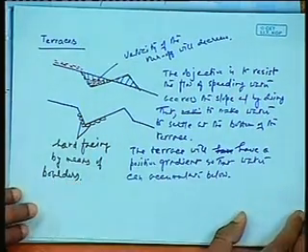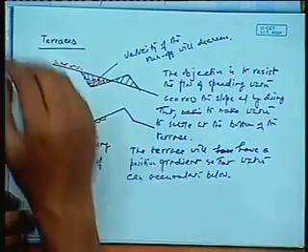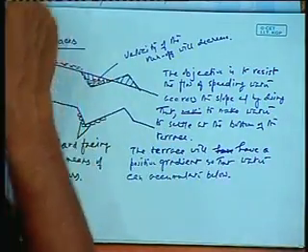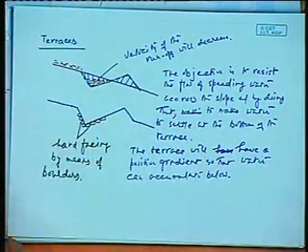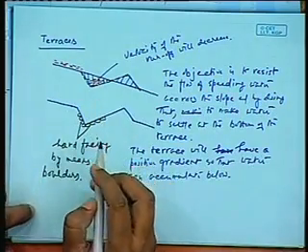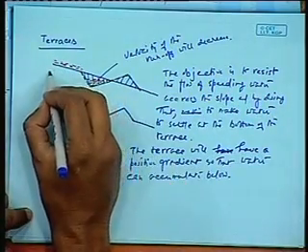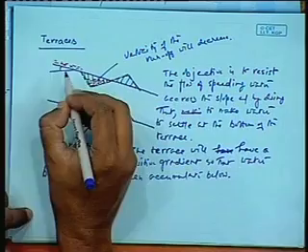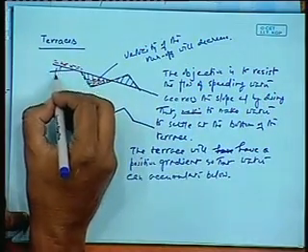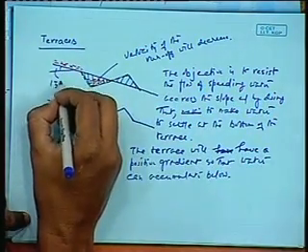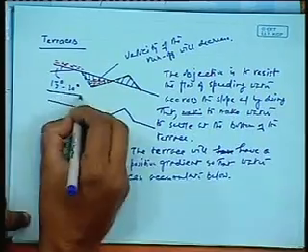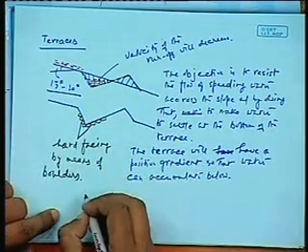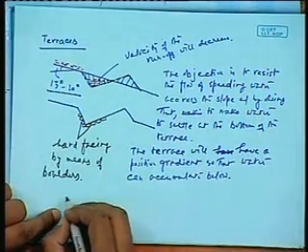So this gives you one kind of terrace. This is called when the slope is gentle. See, the slope here, if you can see this slope, is about 15 degrees to 20 degrees. We generally call these terraces broad base terraces.